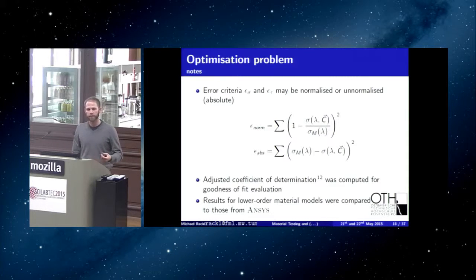So if I was fitting a model using 20 constants, it would tell me, well, you have got a nice fit there, but you use 20 constants. Maybe you should reduce your constants, because you can fit almost anything using a dozen of material constants.